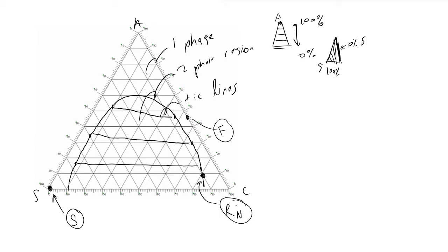And the next step will be connecting the points S and F to define a thing called a mixing point that makes the calculation for the number of trays we will need able to be calculated.